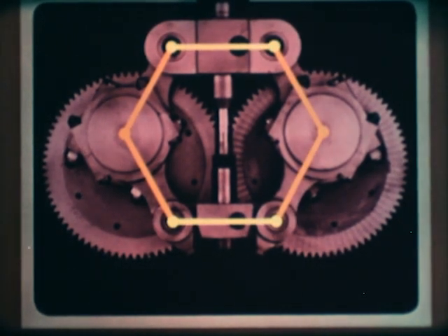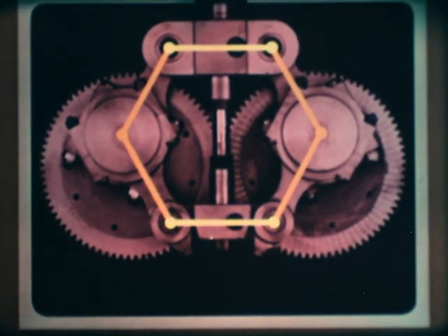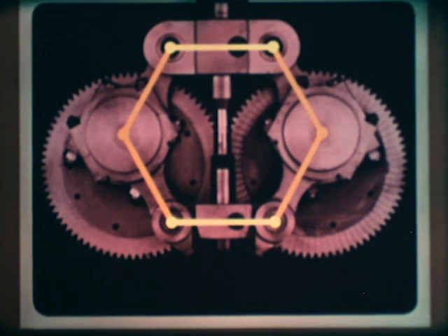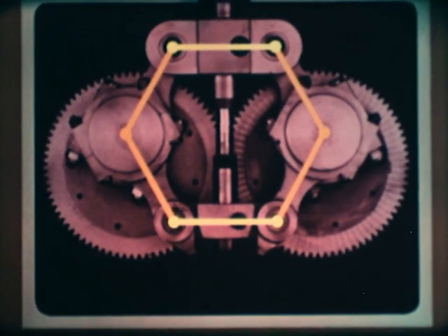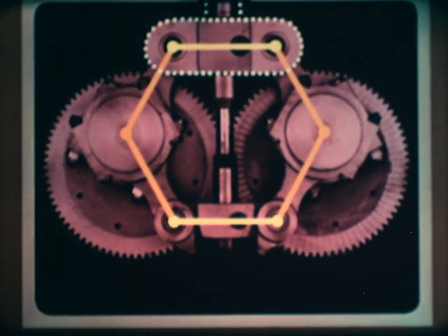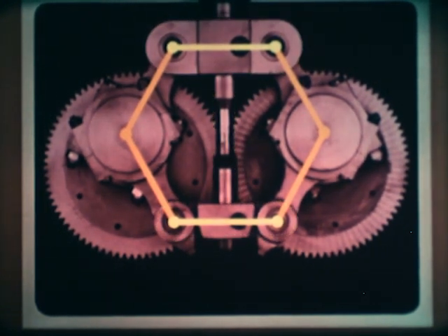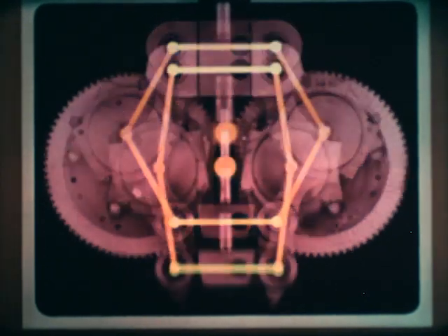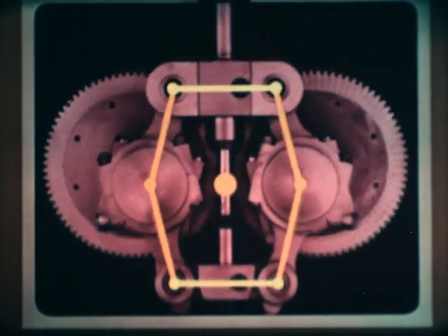Due to the symmetrical build-up of the drive, there are no resulting inertia forces in the horizontal direction. Furthermore, the vertical inertia forces acting in the mechanism will not be affected on the assumption that the masses of the pistons are concentrated in their respective yokes. If these masses are equal, then the center of gravity of this rhombus will coincide with the geometrical center. The center of gravity is displaced vertically.